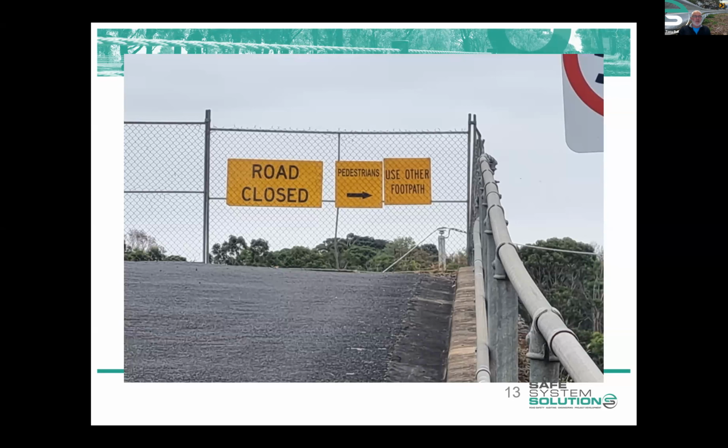I can't answer for the councils as such, Ken, but I know the departments, such as the Department of Transport and Planning, build it into their contract specifications. So they will say that this is a reasonably complex type of contract. We want you to undertake 3 road safety audits, one at design stage, one at middle of construction, and one post-opening.